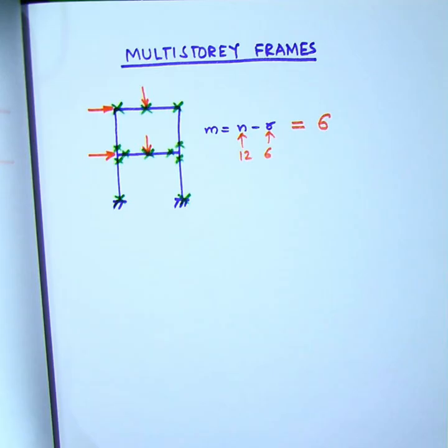So the situation is different from, say, the topmost beam column joint, where for example the beam and column members which are meeting have the same bending moment. So the hinge will be formed at either of the 2, but it will be considered as a hinge in the joint. But in the case of these first floor joints, there are 3 independent hinges which could appear in the 2 columns or the beam.